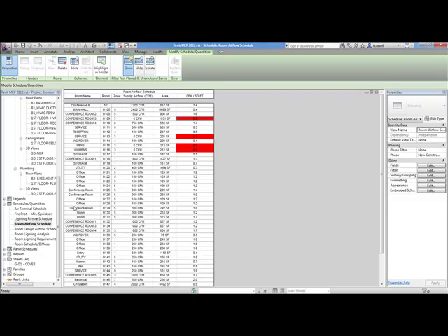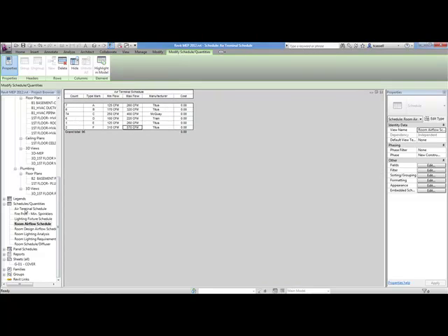And because all of this is automatic, if I go check my air terminal schedule that I've created, I now know that my air terminal count schedule that I had opened earlier is accurate, because this is reading from the model in order to count how many diffusers I've actually put into this model. So I've put in 74 type C diffusers, which are McQuay diffusers, and have a min and a max flow for CFM. Now I want to take this schedule, and you know what?